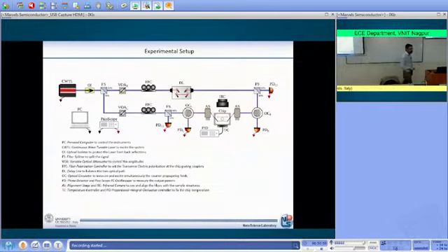By using this system, we can decide whether to insert the light from this port or from this other port. And we can measure at the same time the light that is reflected back and the light that is transmitted. Therefore, by using this kind of experimental setup, we have complete access to what is happening inside the microring resonator, and we can do a lot of interesting measurements.